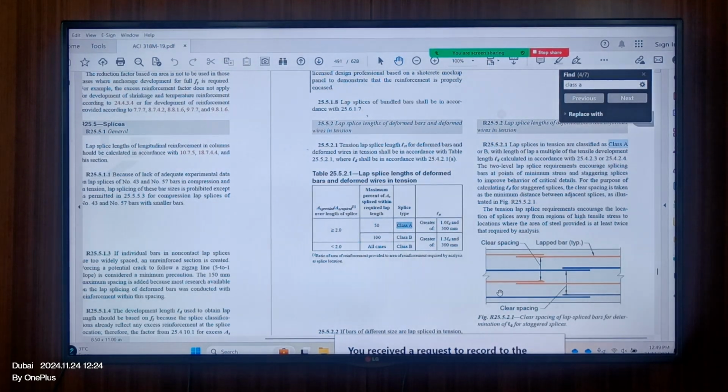Maybe there is a big shear wall length, and they unnecessarily ask you to take the whole rebar and bend it. You getting your point? These things, mostly not in terms of execution, 90% you will have in the shop drawing stage. When you submit the shop drawing, the consultant will review it and give comments.